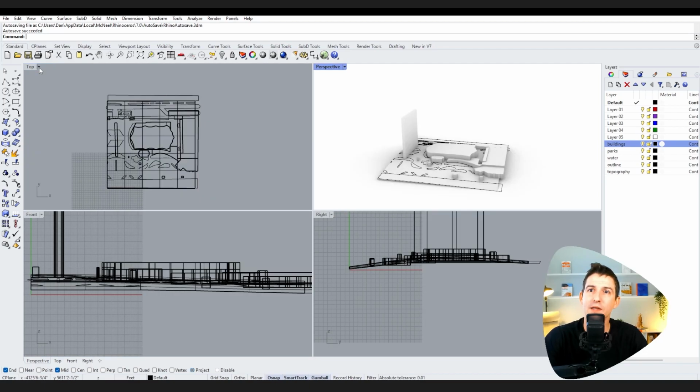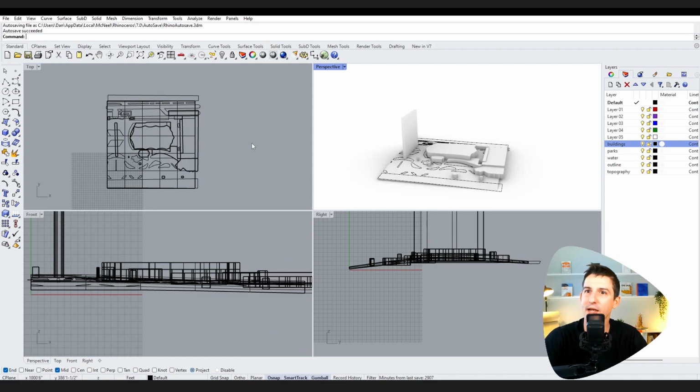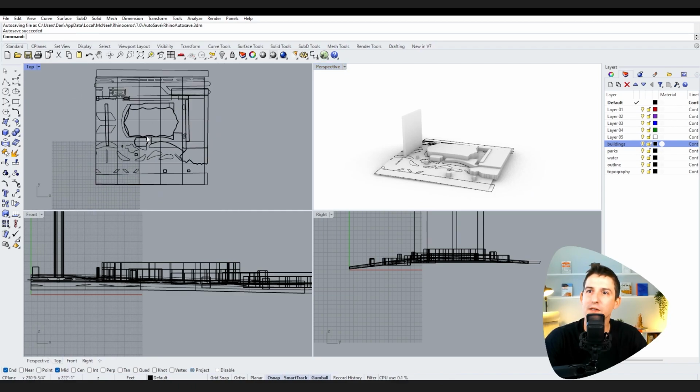So if I double click on the view menu, if you're new to Rhino, that'll get you full screen or back out: top, front, right, and then your 3D, kind of a typical layout for CAD programs. And then in the top view, we can type in the command distance. And if we have the project icon on for the O snaps here at the bottom, then when I snap, it's going to be on the same plane. It's going to be in that top construction plane.